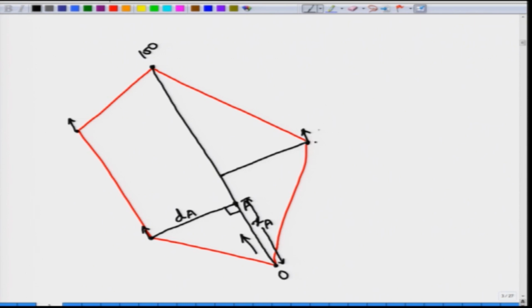So, you have O P Q R S. Now, when you have reached this point, let us call it B. In this case, you measure the distance of B from your starting position using a chain or a tape, and you measure the distance of the point to the right of B. Now, you carry on further, and you have reached this point C. Here again you will measure the x C and you will measure the d C.